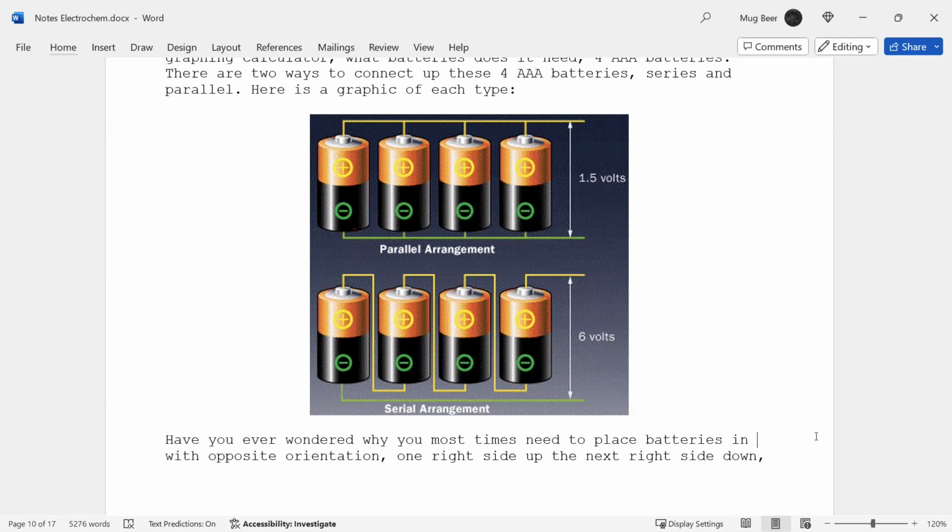So the 12-volt batteries aren't hooked up in series to make 24 volts. They're hooked up like this. So what they did is they just made a bigger battery with 2 batteries. So the batteries are in parallel to each other. If you rearranged it, the truck wouldn't turn on. You'd actually burn out the alternator if I tried to shove 24 volts through.